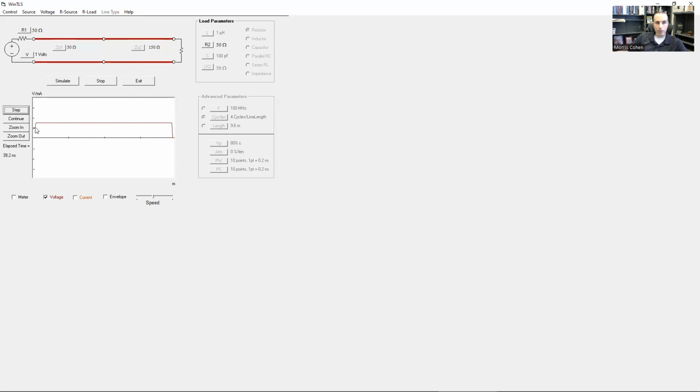All right, remember also the voltage at the source will be absorbed and gone forever. And there's the reflection. All right, so here's the 3/4 coming in, and here's half of that now coming as a negative wave that's wiping out some of that voltage. All right, we can keep this going. I'm going to continue this, in fact, speed it up so you can watch this process play out. Here's the reflection at the junction again. We're going to get some back and forths.